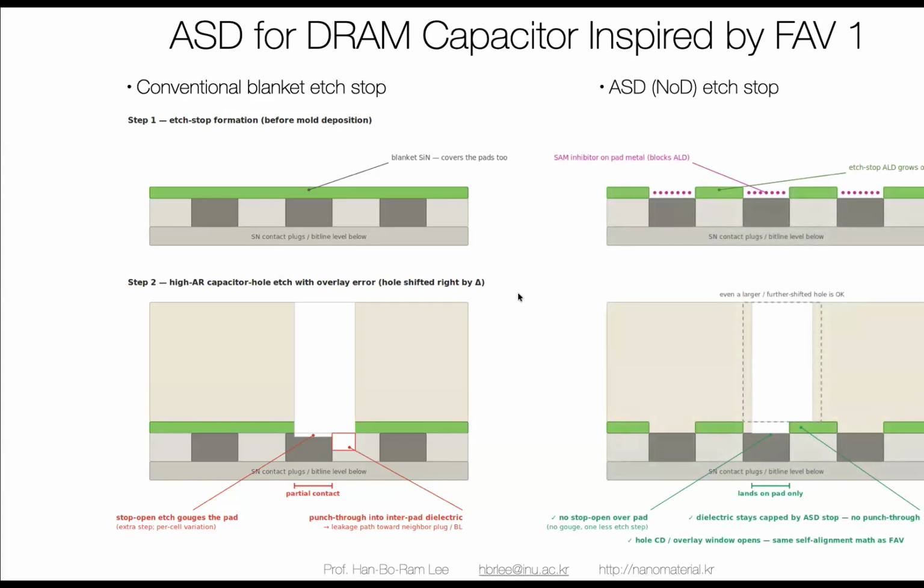So this is the original, and then this is the nitride, the metal area and the nitride. If you passivate this metal area and selectively deposit nitride on it, we can have a fully self-aligned via, same thing in here. And because this area is protected by selectively grown silicon nitride, we can have this structure.